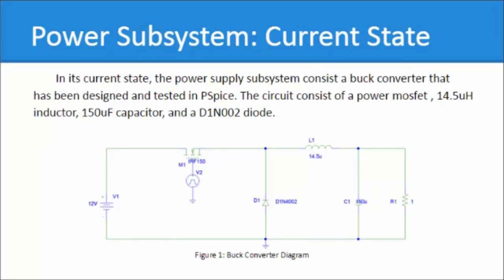The buck converter consists of a diode, inductor, capacitor, and power MOSFET. It steps down the input by turning the power MOSFET on and off. This in turn prevents the circuit from running a high current through itself at all times and also shrinks the input voltage based on the percentage the switch is on.